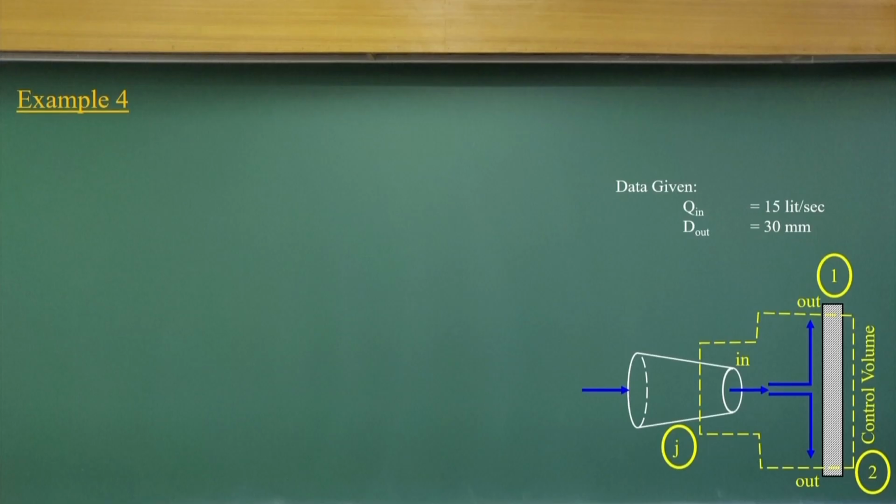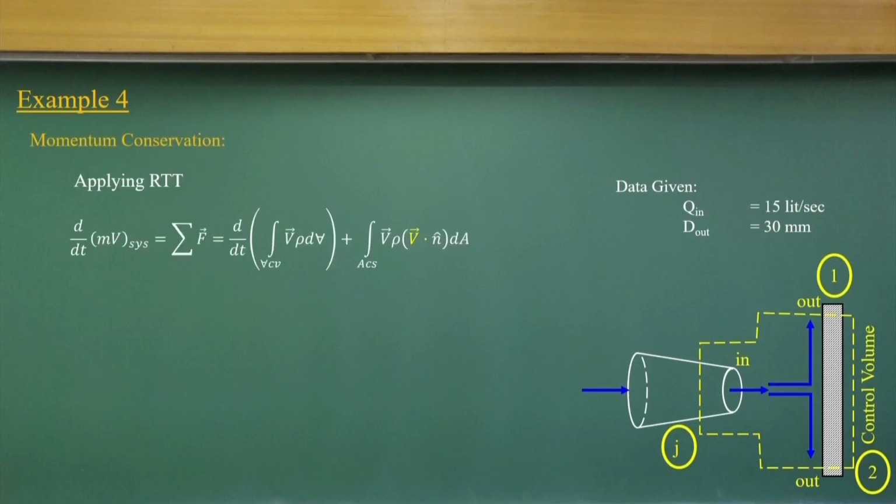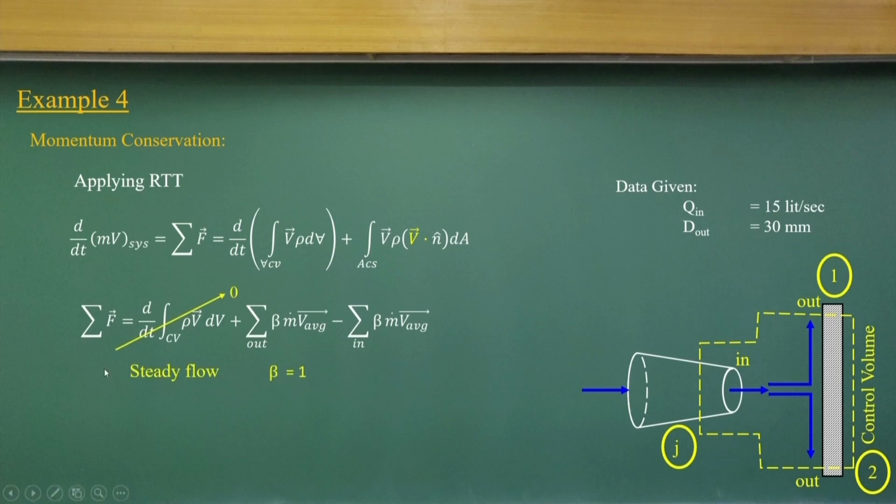And now you apply the momentum equation. The momentum conservation equation we can also apply for these control volumes. Another control volume we have considered is the one around the point of impact. Then we write the Reynolds transport theorem here, force is equal to these components.